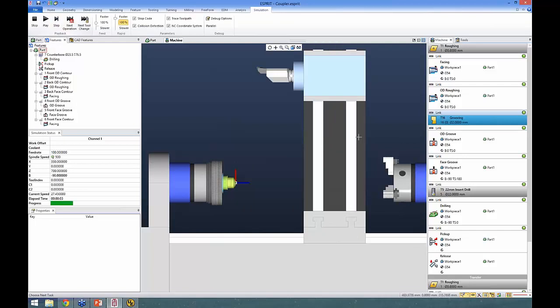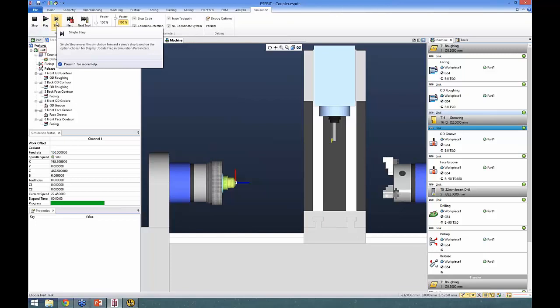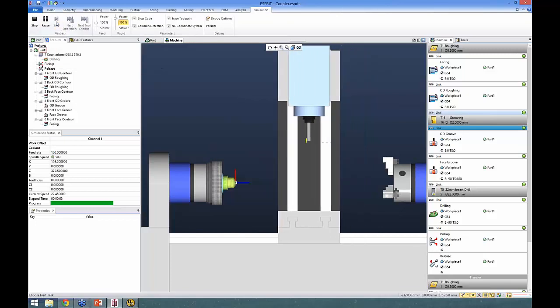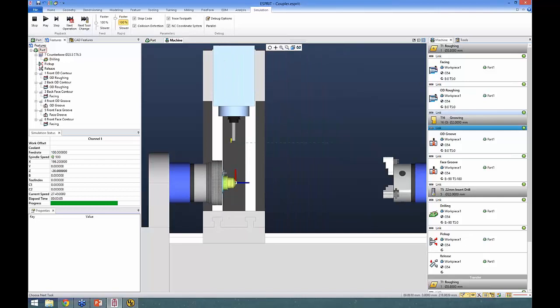The tool change takes care of indexing to the minus 90 degrees position. We load the new tool. And now, as soon as I've started the next link, the head is already rotated to the B0 position. So in fact, the tool change took care of indexing the B-axis to that machine position. So now once I start the link, we start at B0, and all we do is approach the part.